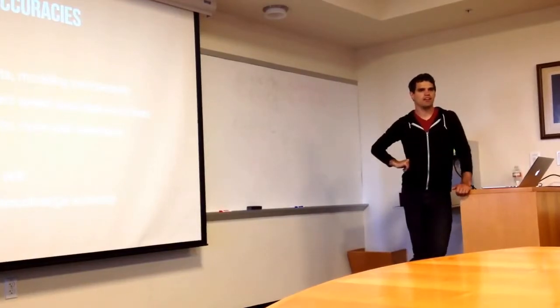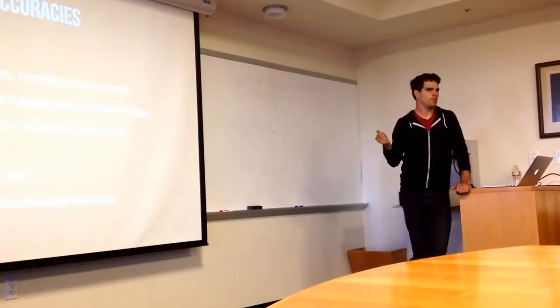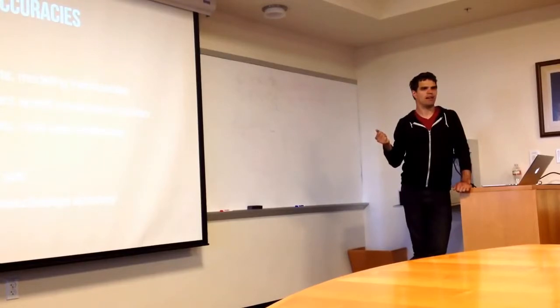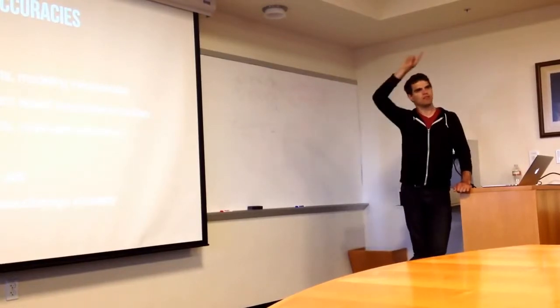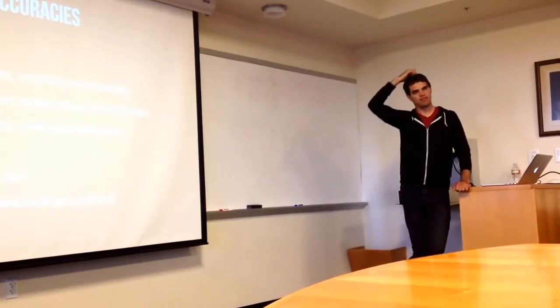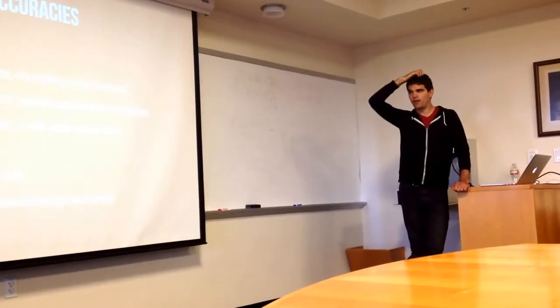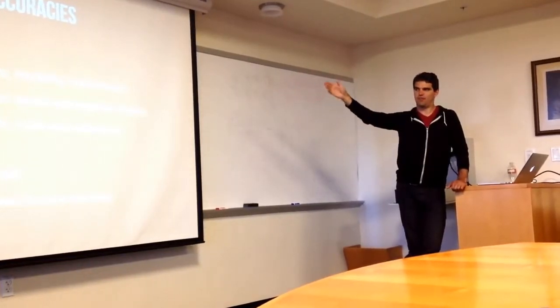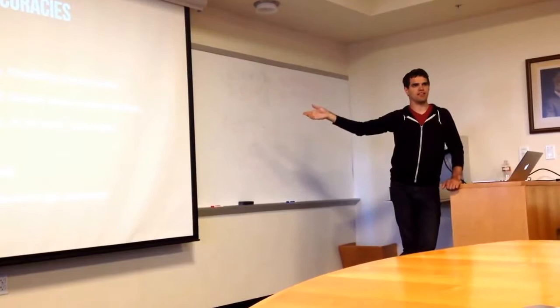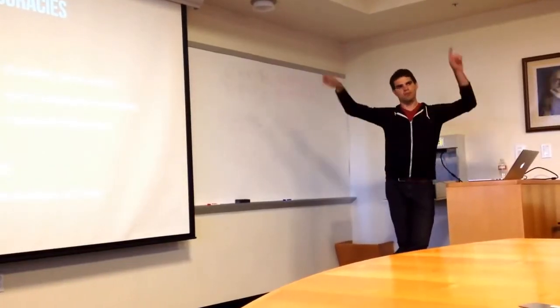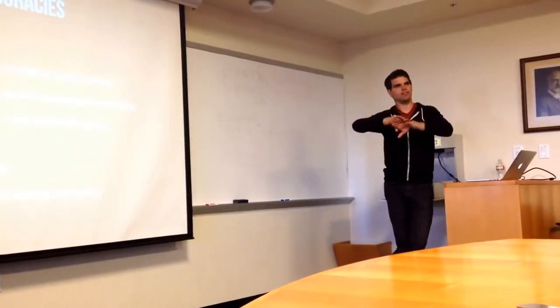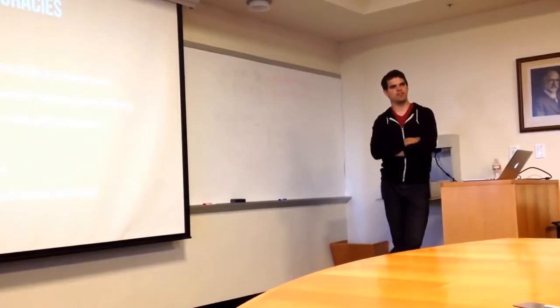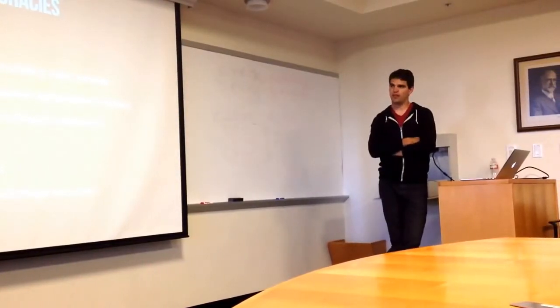This is where you think you're getting a GPS signal directly from a satellite, but it's actually bouncing off some wall. Or similarly, signals take multiple paths to get to me, constructively and destructively interfere, and so reduce my ability to receive them.